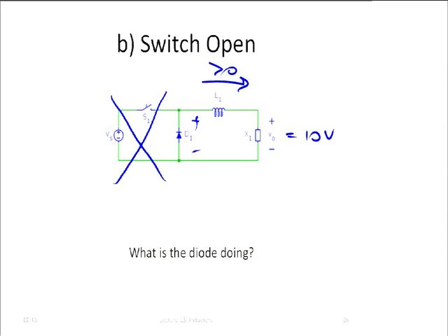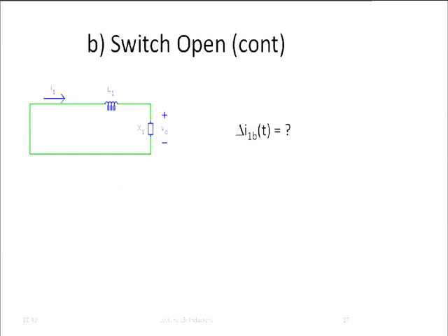What is the diode behaving like? Exactly, it's behaving like a short circuit. So how do I redraw the thing? Okay, so that's what we have here, right? Now we have exactly the same situation again. This voltage is going to vary a little bit up and down, but if it goes up and down by 100 millivolts or so, we're not going to get now into deep differential equations, right? We're solving it simply to understand how it's working and how to design it, not to do mathematical exercises.